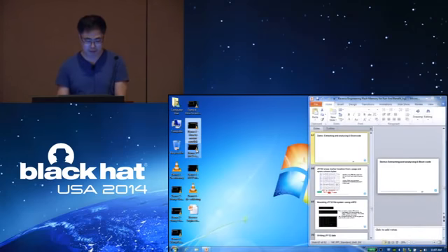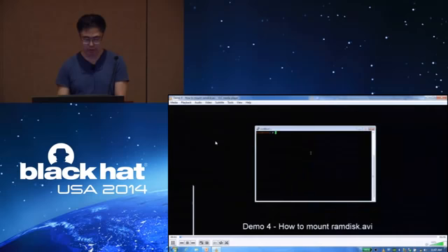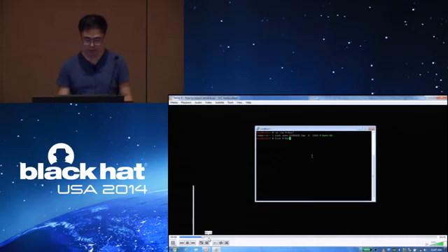But if you copy the image you just acquired to the Linux machine, it is almost 8.4 megabytes. And if you use the file command, it actually shows that it is an ext2 file system. And using MTD RAM or an MTD device, you can actually mount it.